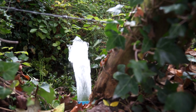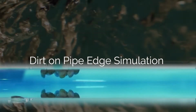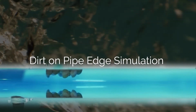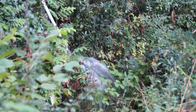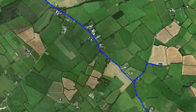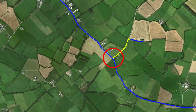Unidirectional flushing uses the highest velocity to scour out sediment and dirt from the edges of the supply pipes. The high velocity of the water carries the sediments with the flow to an open scour valve where the dirt can be safely released. Keeping the velocity focused to a single line at a time is the best way to efficiently complete this process. Schemes should be extremely careful that they are not agitating dirt in other sections of pipework when cleaning recently repaired or small sections of network like dead ends.